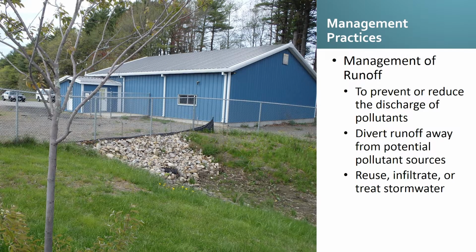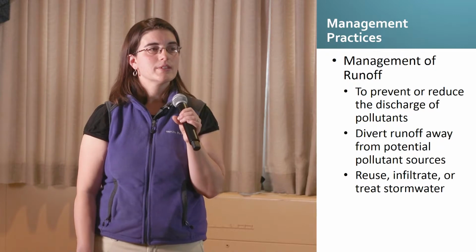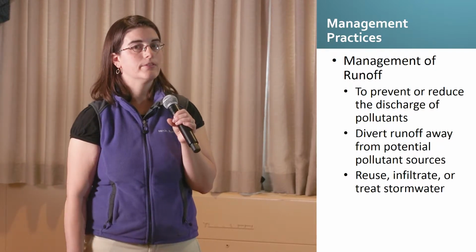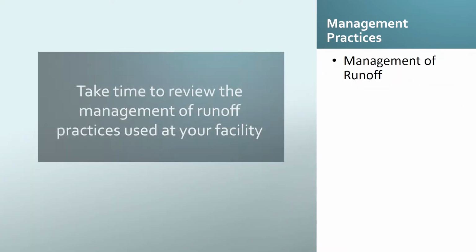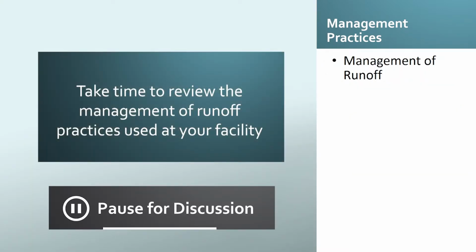So, management of runoff at the facility. The purpose of it is to prevent or reduce the discharges of pollutants, and you want to divert the runoff away or around from the potential pollutant source. You should try to reuse, infiltrate, or treat stormwater prior to it leaving your facility. Take time to review the management of runoff practices used at your facility.